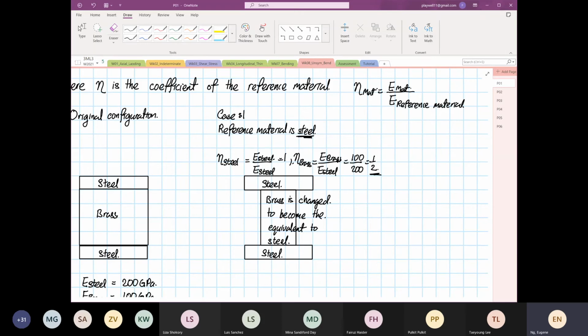So the strength, the ability to withstand the structure, is the same, because we narrow it down. So brass you have to have thicker, steel you have to narrow it down because the Young's modulus is twice. Okay, let me now do another case. Yes, someone has a question.